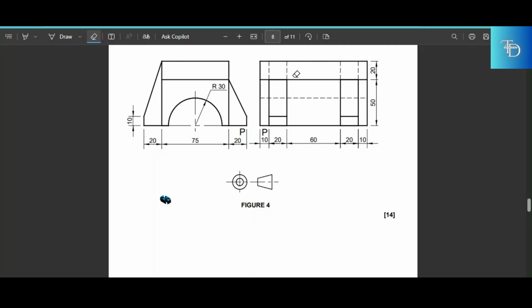Alright, then the reason why we're here is to explain the hidden details for that web right there. So we have two pairs of hidden details. We have 1, 2, and then we have also 1, 2. So what does that tell you? The reason why there aren't hidden details here is because they are also web that can be seen from the right view, which is this web. But pay attention to this. You see the total height of this web, it ends there at that 50 units. But the total height of the opposite web goes all the way to the top side.